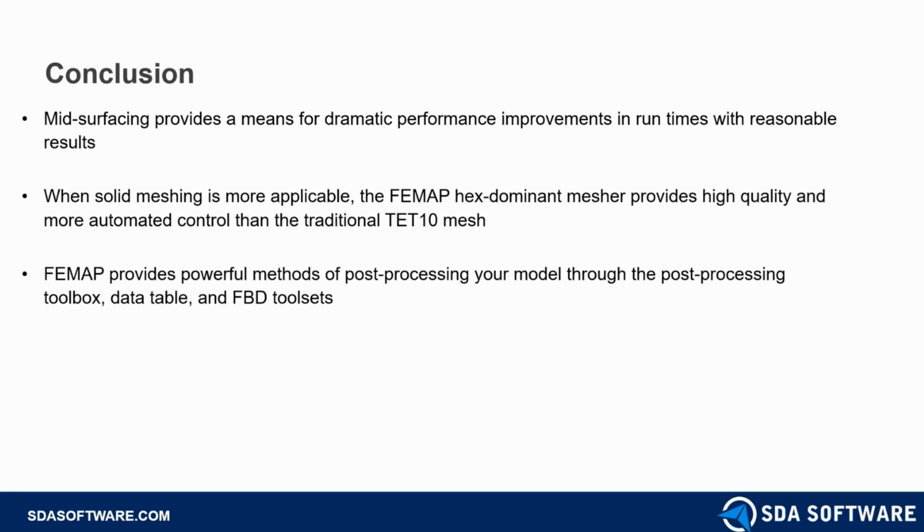I will tell you honestly, yes, it does take longer to do the meshing. The TET 10 meshing is much quicker, but it's not dramatic. It's like, okay, maybe 10 times, 20 times longer, but given what it does and the quality of the result and how much time it saves you versus the traditional hex meshing techniques, it's well worth it.